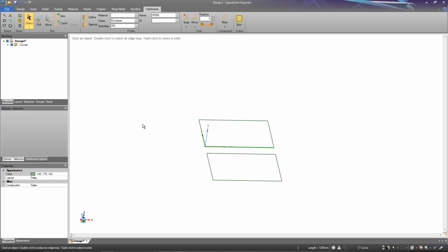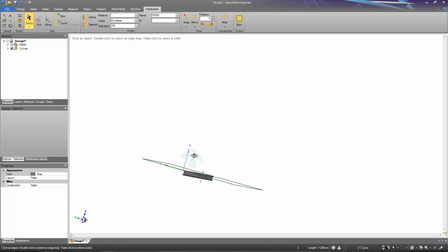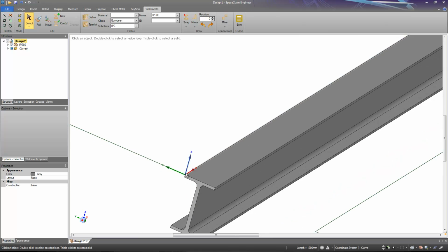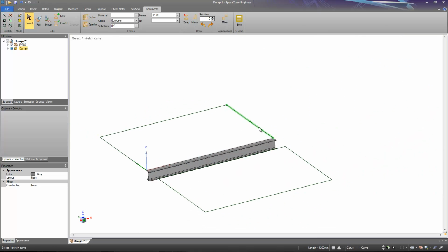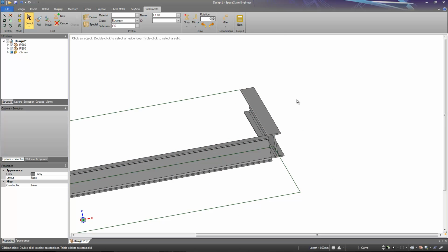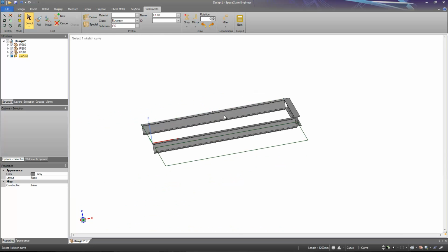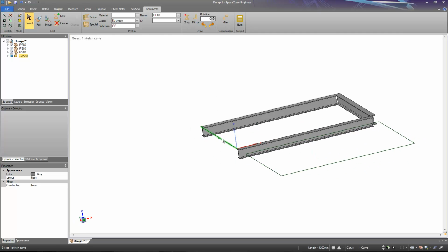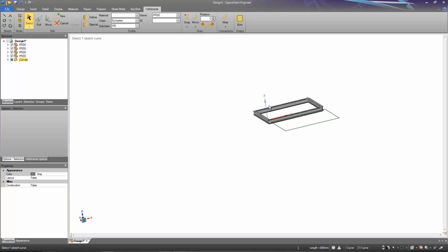So if I start by selecting just one line and click on New, you can see that in the direction going in this case from left to right, the beam is here is the left top. If I select this beam and click New or Continued, I will see that the beam is again placed from this starting point upwards to there. Then if I continue, click here, this beam has the same orientation as this one, and this beam will have the same orientation as there.